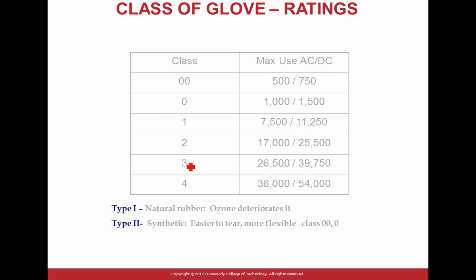Okay, here are the gloves. You guys use gloves, right? 3M has gloves for you. Here's the gloves requirement. You are looking at class 0 here. So look at class 0, gentlemen. Class 0 can show you how high you can touch. So you grab a class 0, and I can, with my bare hands right now, touch up to 1,000 volts AC or 1,500 volts DC, like this.